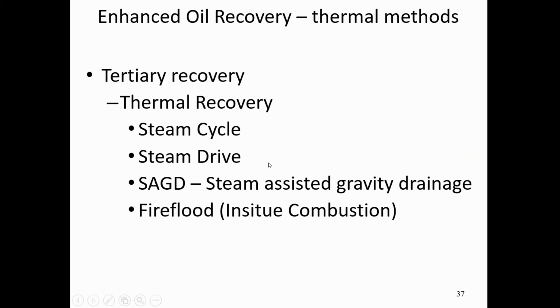And in thermal recovery, the major aim of it is to reduce the viscosity of the crude oil, to make it easy to move, easy to be swept. So thermal recovery is very much targeting viscosity in the Darcy equation. And how can I increase the temperature of the reservoir? Either by injecting steam, or injecting hot water, or use a fire inside the